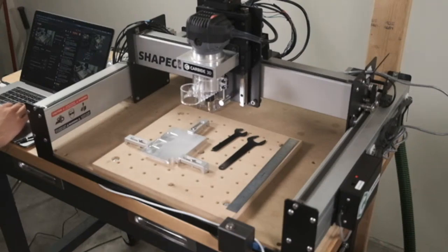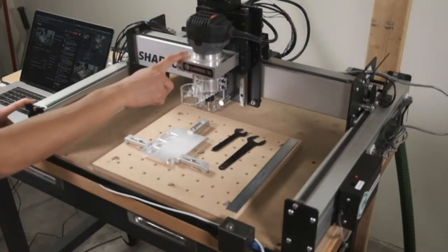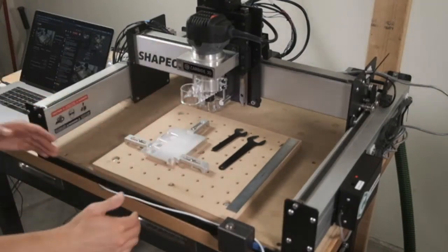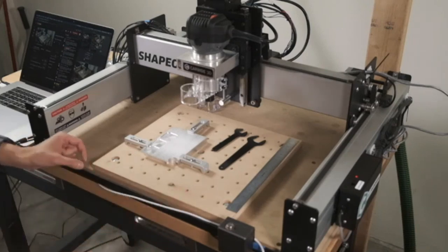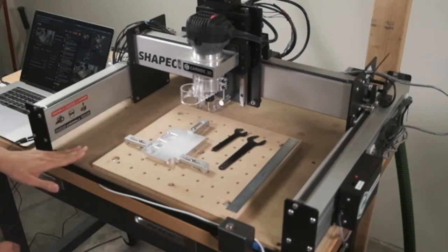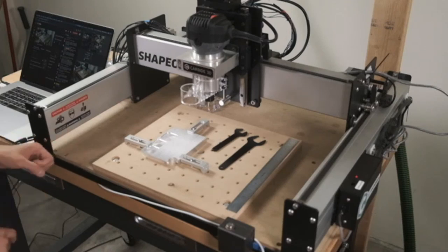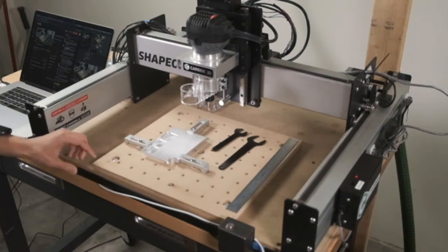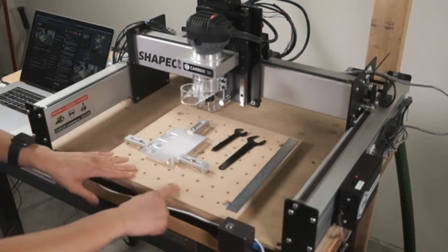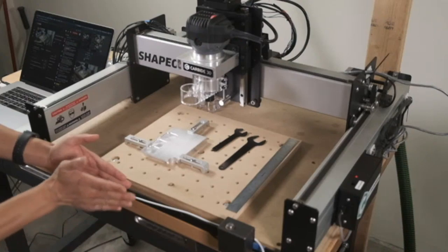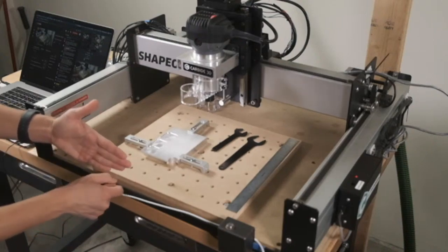Can you talk about mounting stock on the front to mill dovetails? Sure. So right now, Shapeoko has a bit of overhang capability. You see it when you change a tool, it comes in front. If you want to hold stock to the front of the machine, the newer machines have a little bit of a lip here that extends up, I think, 3/4 of an inch over this MDF. So you could either take a large board and clamp it to the front base frame, or what I've done before is build up a little MDF platform here that extends out so that you can clamp stock to that front face without hitting this.